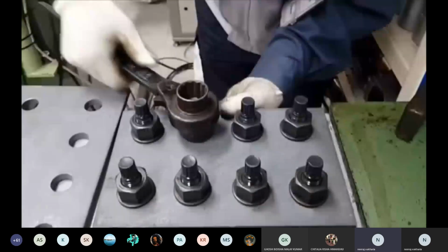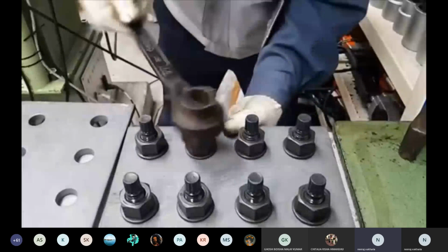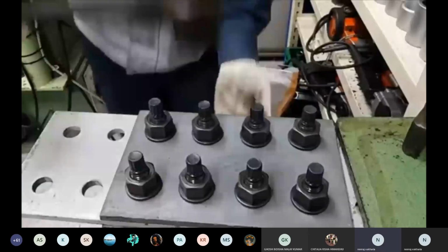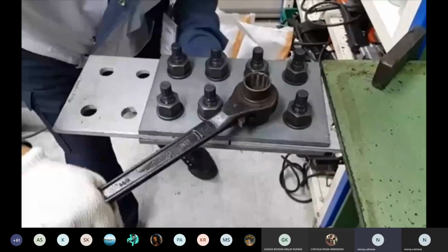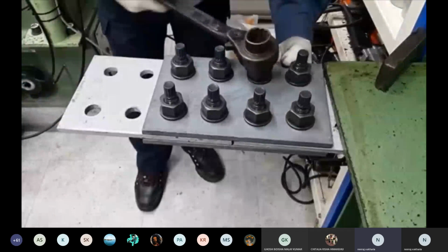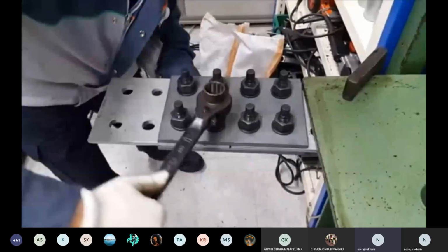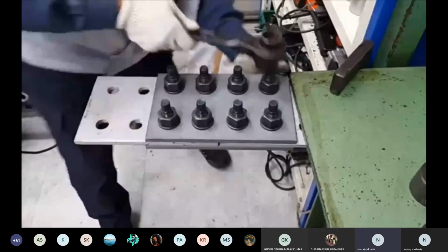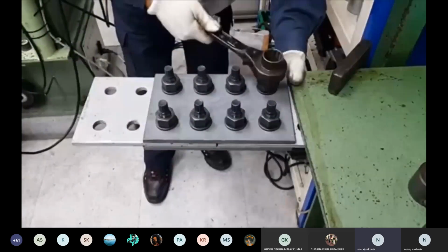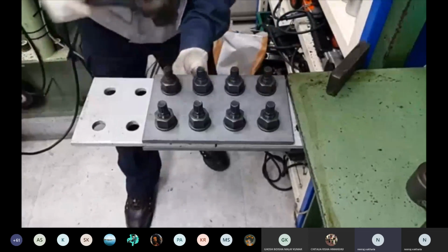In welding you have to scrape out the whole weld and re-weld everything, but with bolts you can just change an individual bolt if there is any problem. So bolting is the most preferred connection used nowadays. But to connect the secondary beam or the smaller members, they are generally welded on site. The primary connections use bolting.